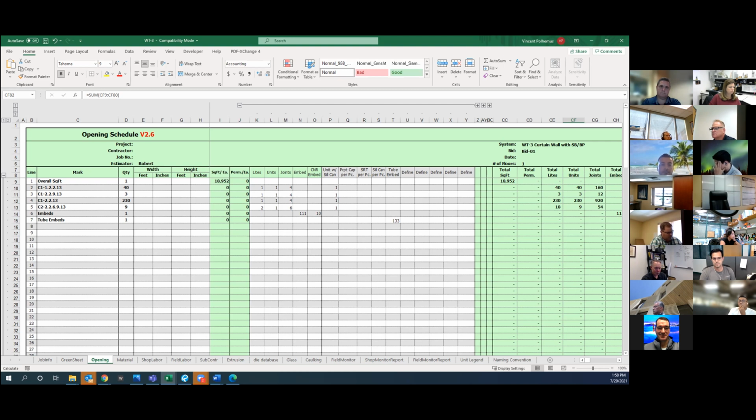And so the panel count would have a direct impact on the amount of welding, right? Correct. You'd literally have a line item for every panel on the job, or at least every unique panel size, and then a count of how many there are. So for each panel I'd say, here's the stretch out of the panel, here's how many bends that panel gets, here's how many inches of weld that panel gets. And then that panel, you've got 25 of them. At the bottom, it summarizes so they get the total, but they're basically taking that for each panel and inputting it into the programs they use to get their pricing.